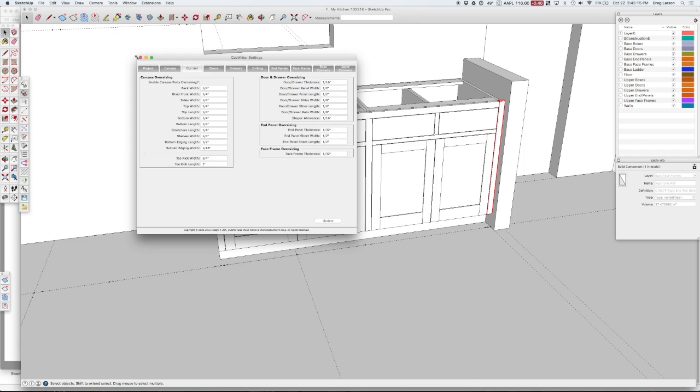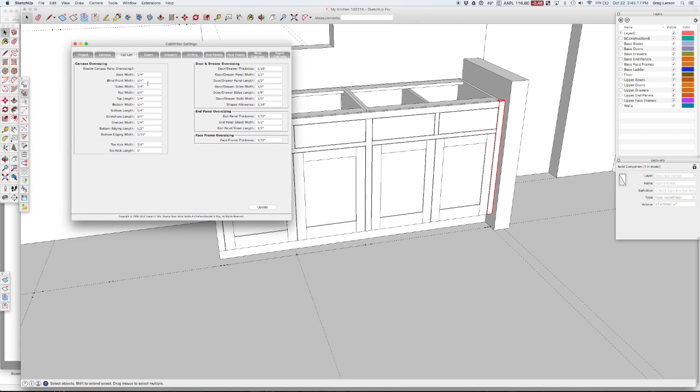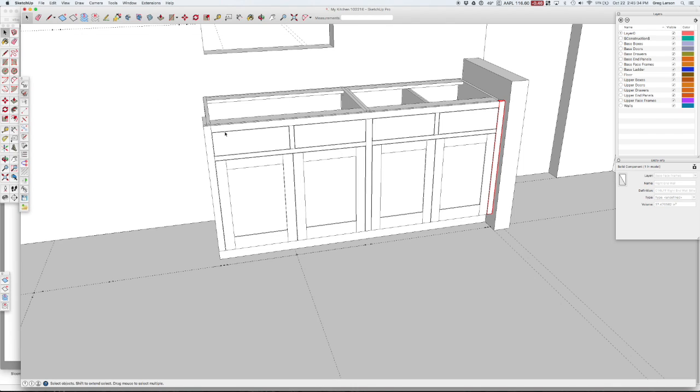If you go to the cut list tab and you want to have face frame oversizing, you can oversize the face frame thickness, and I've chosen to do that by a 1/32 of an inch. So that's where that extra 1/32 of an inch comes from. And that's applied to all parts on the face frame. So our wall style, what that gets us is an additional scribe allowance if we want it. And what an opening style gets us is this filler piece.